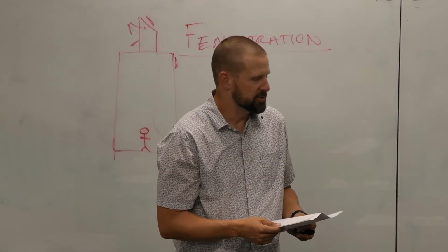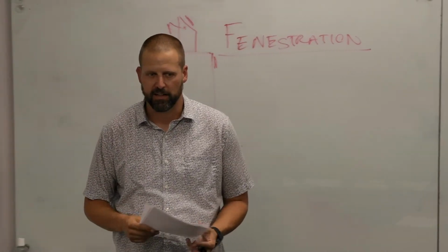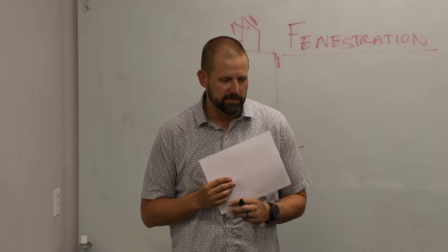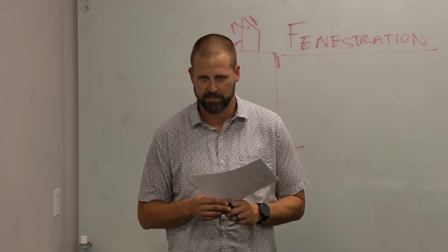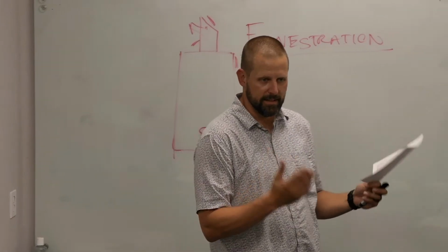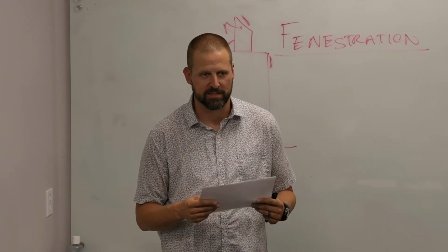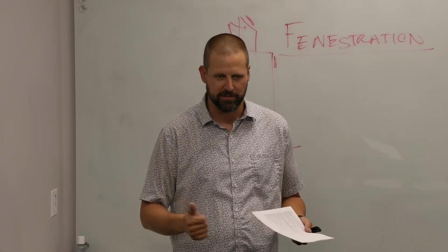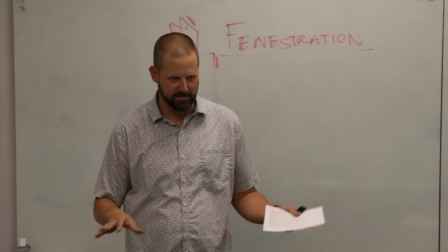Generally, heating does not drive our market. Generally, we do a lot of rule of thumb type stuff with the move towards decarbonization in our market. It's costing a lot of money, so we will probably be spending more time thinking about heating loads. So I've seen a handful of presentations that rule of thumb heating is generally 10 to 15 BTUs per square foot. And that's a good place to start if we're pricing something up.